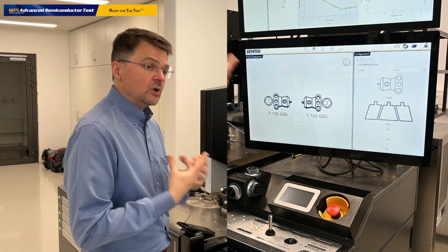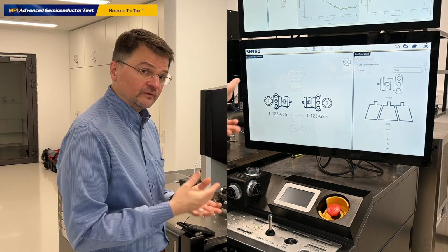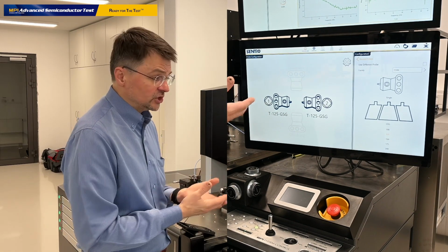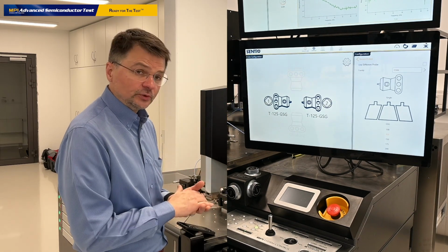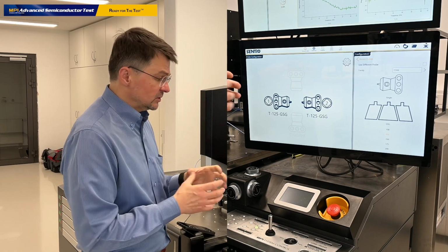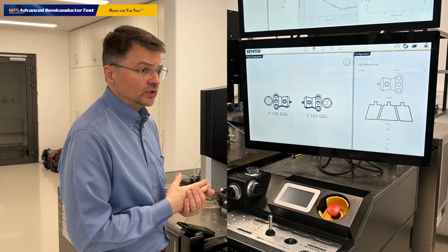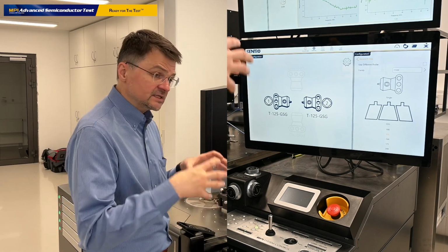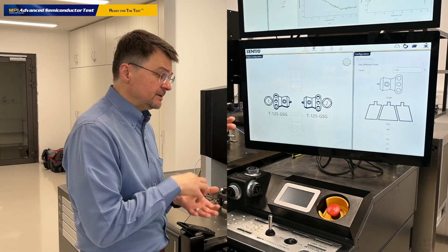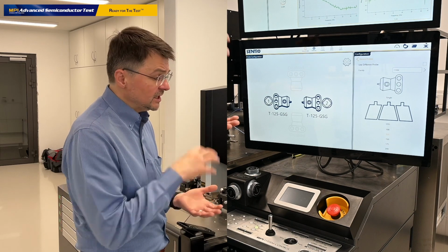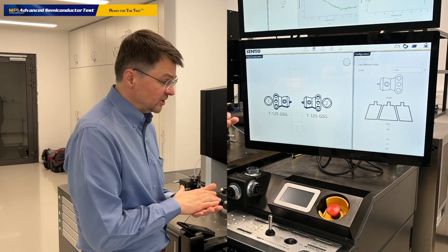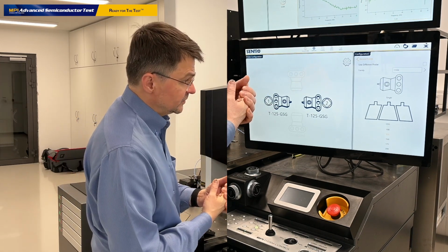It changes the models of calibration standards we use for the calibration, like open capacitance, load inductance, and short inductance, because every probe has a slightly different set of these coefficients. It doesn't change models for the transmission lines, because the electrical characteristics of transmission lines depend on the design of the calibration substrate, and we use the same calibration substrate, which is AC2 version 2.